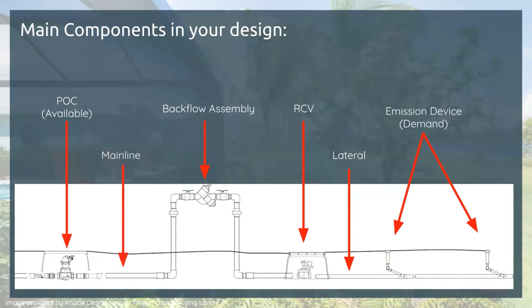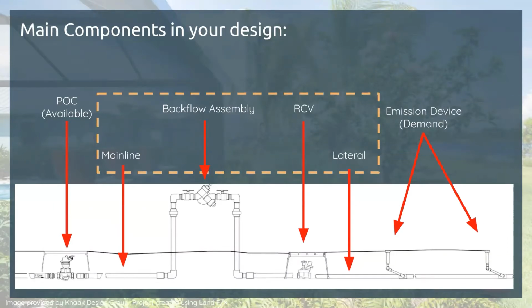What we're going to consider the middle stuff is the in-between stuff that we also need to account for, and really what gets affected as it comes back to cross-checking what we have available at the POC. So it's not just a simple, I'm running my heads at 30 PSI, I have 14 GPM, does that cross-check with what I have available at the point of connection?